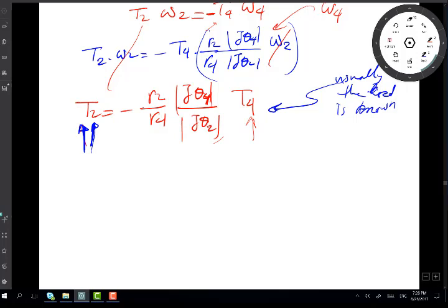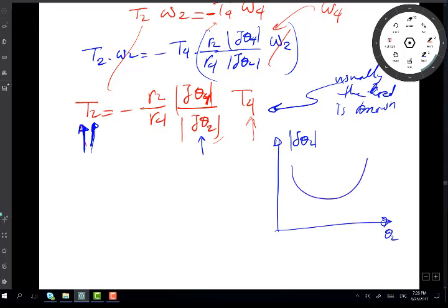Normally the linkage multiplies the input torque to give us the load torque, so it magnifies the input torque for us. When I analyze a linkage, if I have theta 2, I always want to draw this main determinant against theta 2, and make sure it stays on one side of the y-axis. It shouldn't cross from negative to positive, otherwise it will be 0 at some point in time, and this is not good.